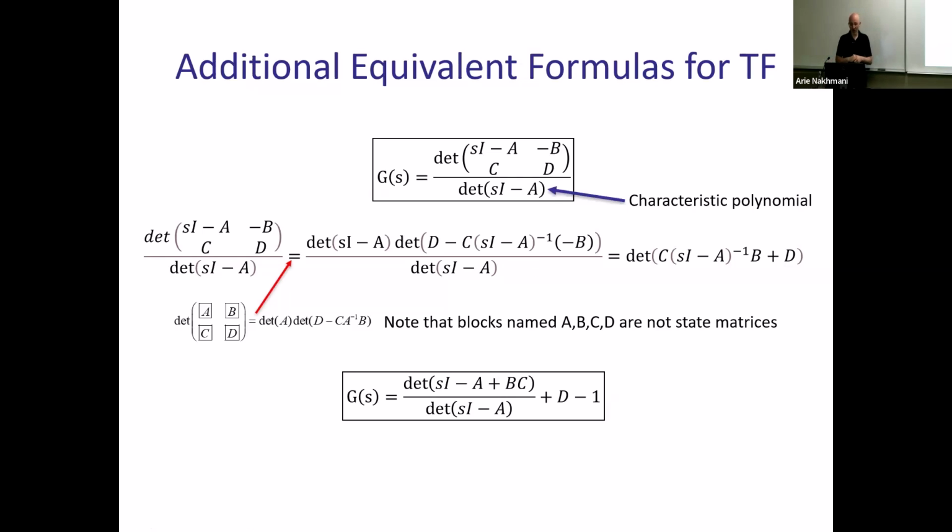Pay attention that at the top you have two polynomials practically, one polynomial divided by another polynomial. The bottom polynomial is the determinant of sI minus A. And this is the transfer function. And what is that polynomial? This is the polynomial of poles, right? You compute poles as roots of that polynomial. So technically, the characteristic polynomial of matrix A is the polynomial of poles, practically speaking.